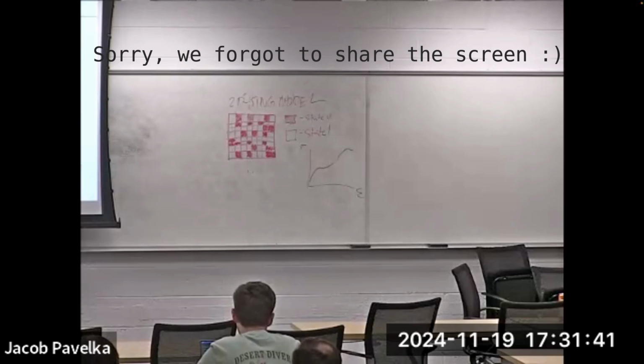What was it in the BCs, how much deformation? Tension BC, how much displacement are you giving? I think it's like 0.05. I think it should be big enough. Anyway, if I wanted to make that dimension bigger, maybe I will do something like that. Change it to 10.